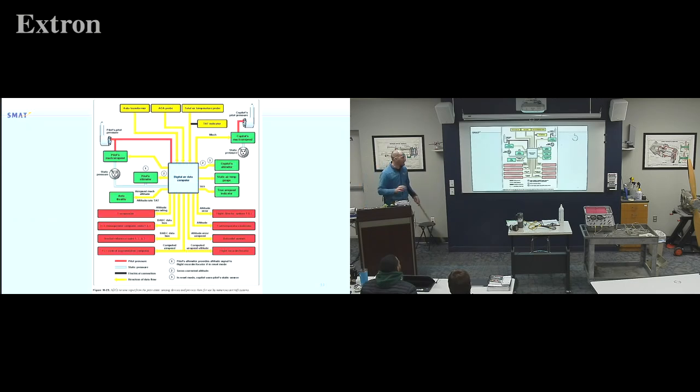So if you go to an air data computer, it's going to look a little bit more like this, where I've got pitot from one side of the aircraft coming into my computer. Pitot from the other side might even just skip the computer and go straight to the co-pilot's. Basically, we're going to use the word backup there: if something were to happen to this system or this computer, we still want to be able to see our speed, so co-pilot's. Same idea here, even on the pilot side, we're going to have an airspeed indicator that can get a reading without the computer running.